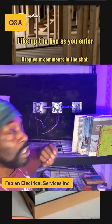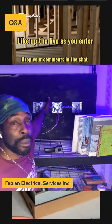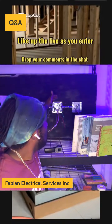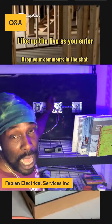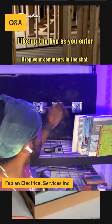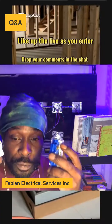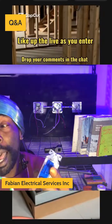So the difference between deep and shallow: when you have a deep box, which I have here, and a deep plaster ring, which I have here, you're allowed to have more wires inside of your box. You can also place a 4x4 extension ring on here if you wanted to have more space inside of your box. So very important, don't forget that your toggle switches and so on do count towards it.